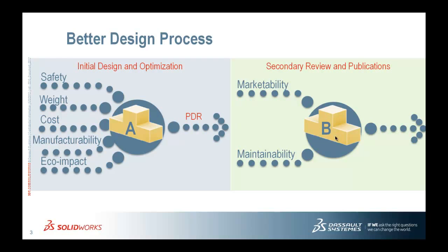We're also very excited to bring to market our new plastic suite of tools that allow us to really look at the moldability of a part. So for any injection molded parts, whether they're multi-cavity or individual parts, we can really take a deep dive and ensure that our parts are going to be moldable. We can look at things like weld lines, short shot, sink marks, shrinkage, and evaluate all those things with respect to trying to make the best design decision. And finally, we'll look at the environmental effect that these different materials will have.